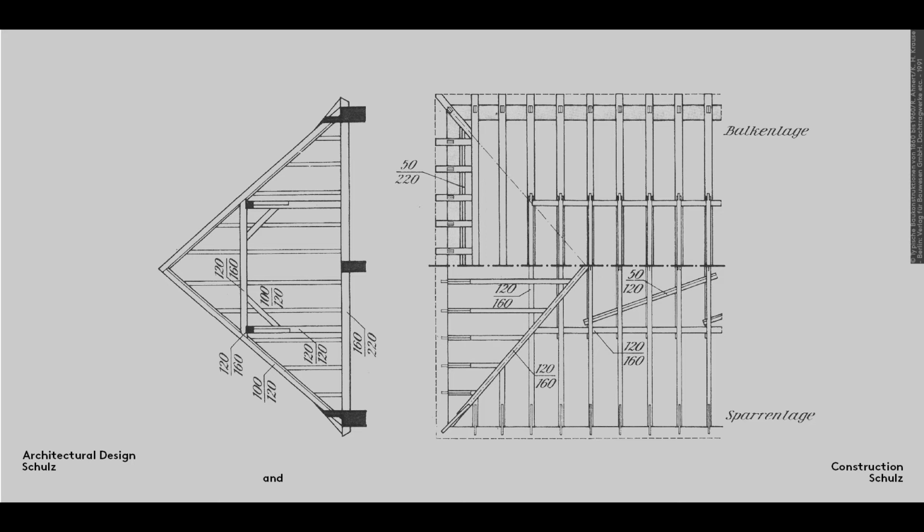It illustrates a purlin roof with two vertical posts and double ties, which should not be confused with structural collar beams. What is interesting in this drawing is the way the plan view is shown in two projection planes. The top half shows the floor joists and the double ties. At the bottom, you can see the rafters with tilting fillets at the eaves. Using this separation into joists and rafters is good practice for the trainee architect.